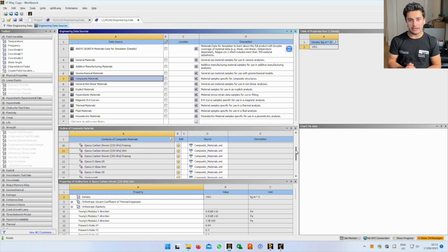should talk a bit about performing simulations on composite materials such as carbon fibre. The material behaviour of composites is far more complicated than for linear elastic materials that you're used to working with, like aluminium, like steel, any of the stuff we normally do in Fusion. And the structural properties of carbon fibre are highly specific on the layups.